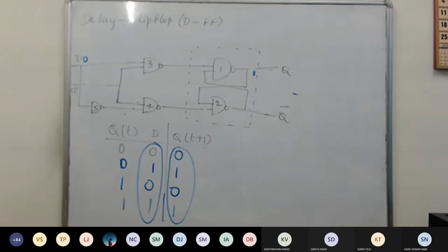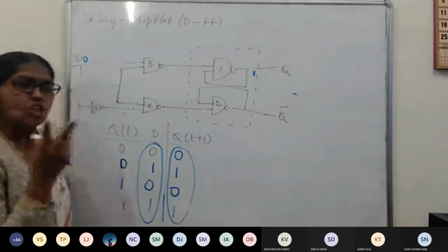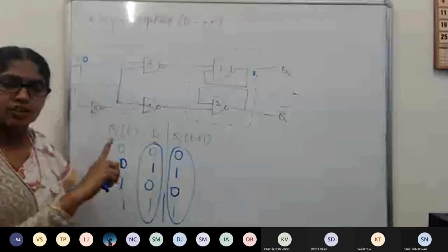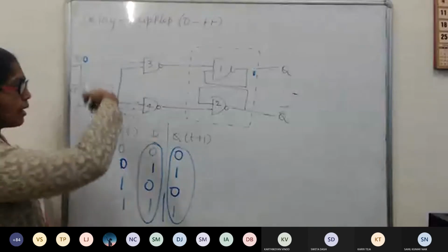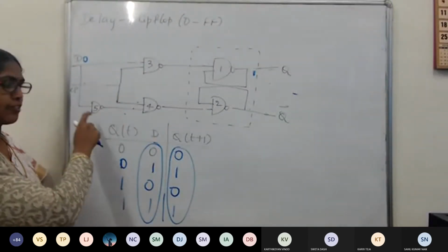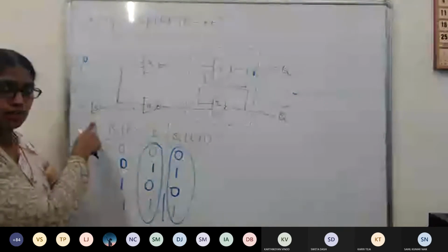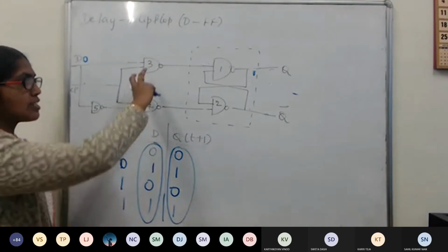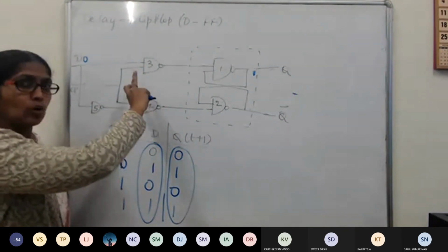Somebody has proposed this and we are understanding it. Now, we should be able to think for ourselves. Completely understand the logic behind it. What exactly is done? Instead of 2 inputs, a single input is taken and its inverse is sent here. In the 5th gate, concentrate on the 5th gate, it's a NOT. Then afterwards, 2 NANDs are proposed.